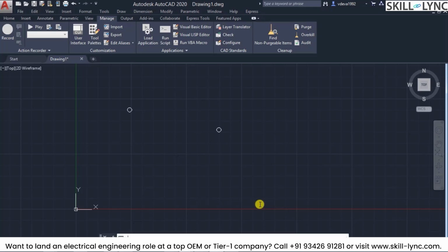So once we click on this, you can see that it prompts us that the load has failed. Why? Because you can see a clue here. In this command line, you can see that once this backslash is pasted, it is no longer visible and it is available only here. So this is the clue. When calling for the load option, AutoCAD cannot treat the single slash symbol. So we have to explicitly specify two slashes to indicate the path of it.